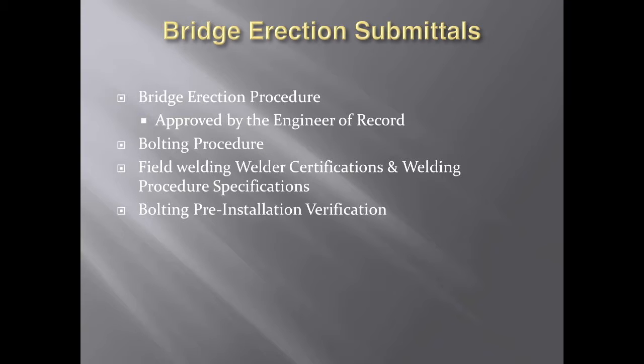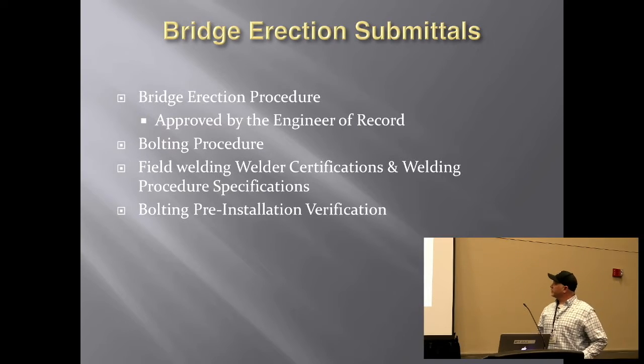Some of the things required on bridge erection submittals are the erection procedure itself, which has to be approved by the engineer of record, bolting procedures, field welding certifications and the WPSs. And then we will come out and help with the pre-bolt inspection.